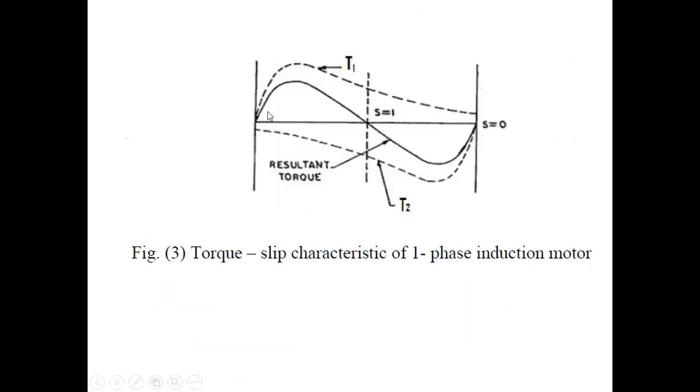So what we are saying is that each of the fluxes phi 1 and phi 2 will result in torques T1 and T2. Torque T1 will tend to be in the anti-clockwise direction as suggested, and torque T2 will be in the clockwise direction. At startup, when the motor is about to start, both torque T1 and T2 are equal. Consequently, this machine cannot self-start. So it requires some mechanism of pushing it so as to move either to the left of S1 or to the right of S1.